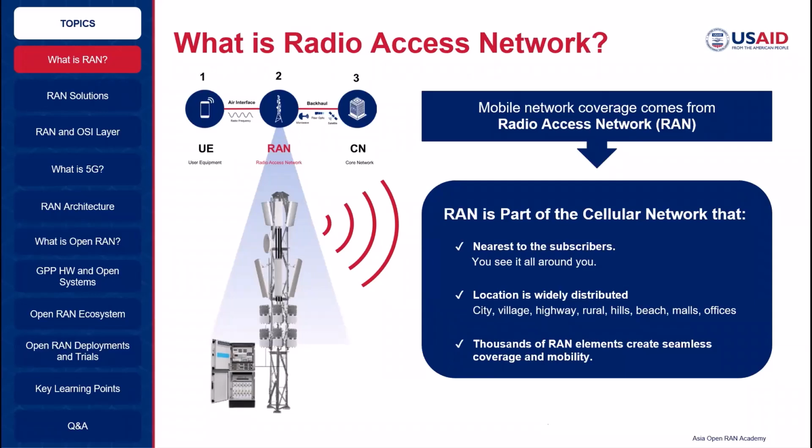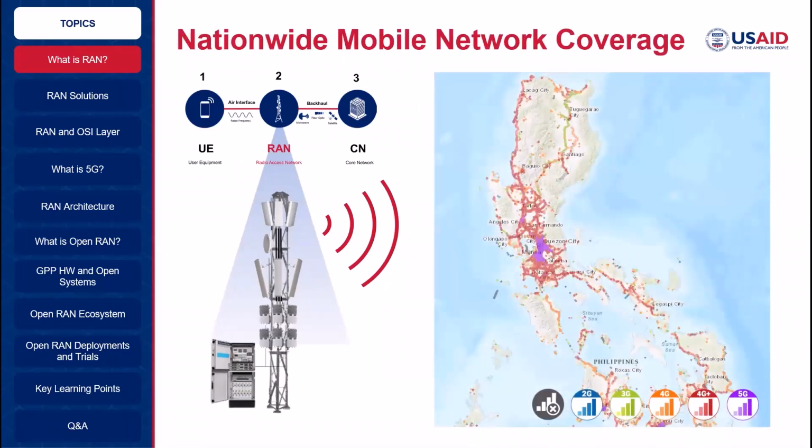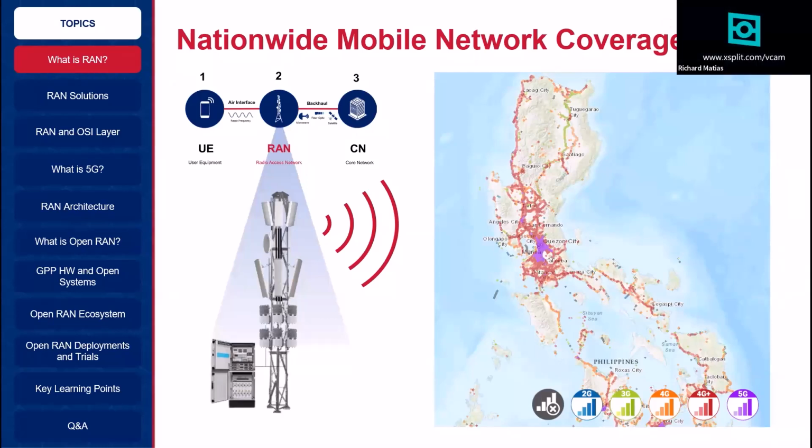Most of the time, our radio access network has an output power of 20 watts, as I showed you in the simulation. Basically, we have a nominal output power for the radio, sometimes 20 watts, 40 watts, or 80 watts. And sometimes, of course, if we use massive MIMO, where the electromagnetic energy is concentrated in a single beam, we will discuss that later, the power becomes higher.